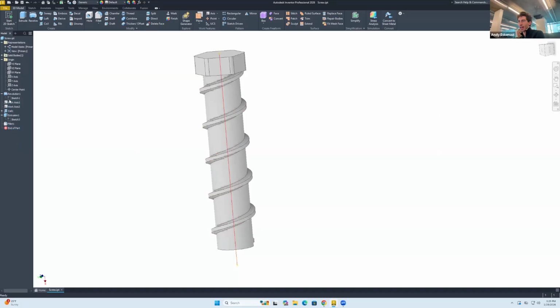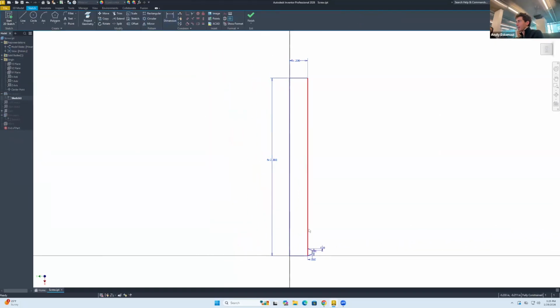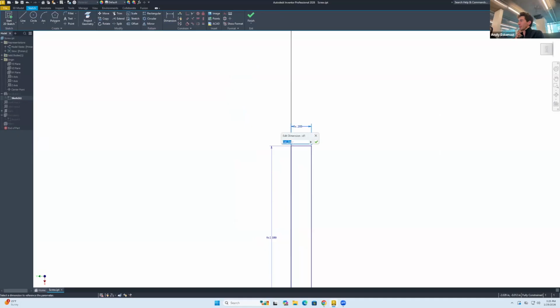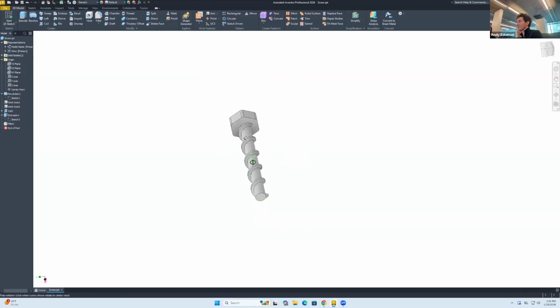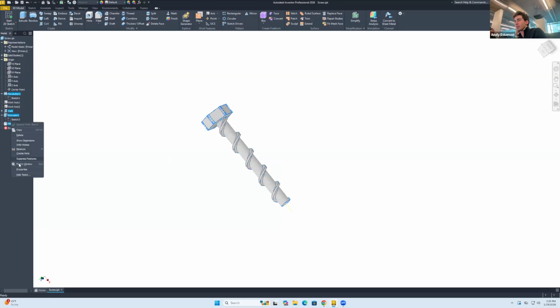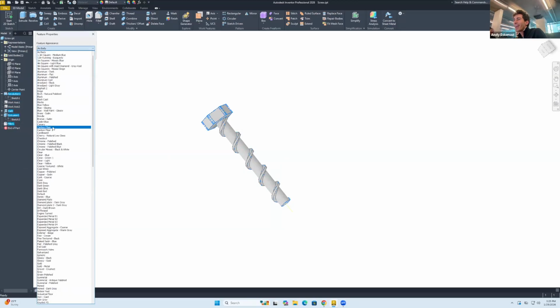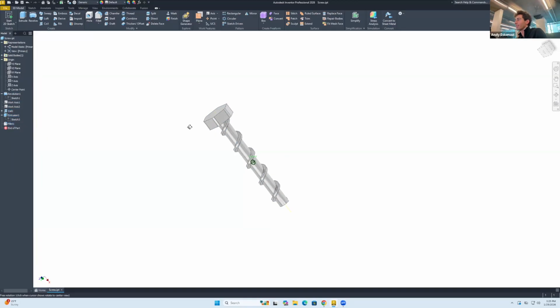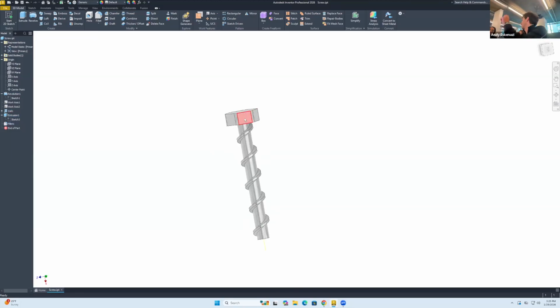Again, now I'm realizing that I'm going to go back to this sketch. This one we called the dia, but it's technically the radius, so I'm going to divide that one by 2. There we go. Interesting looking screw, but it's technically fully defined by those 4 parameters right there. Just because these things are very cool, let me make this chrome, because why not? And now you've got a chrome looking screw. Perhaps the only other thing we could do is modify the head height if you wanted to, or something like that.